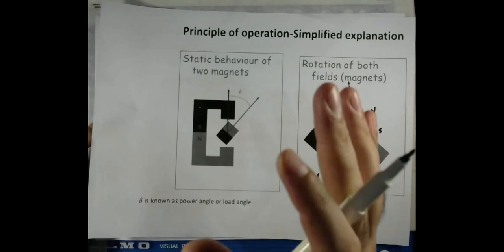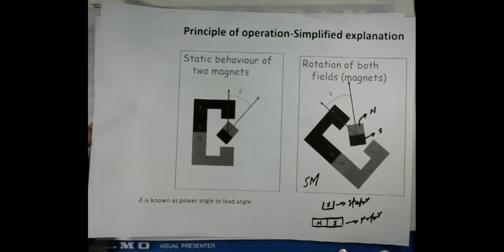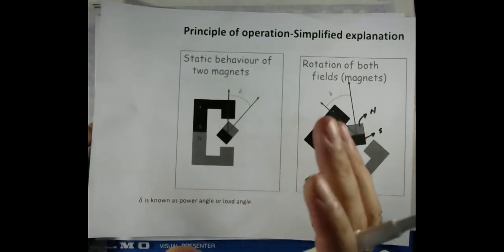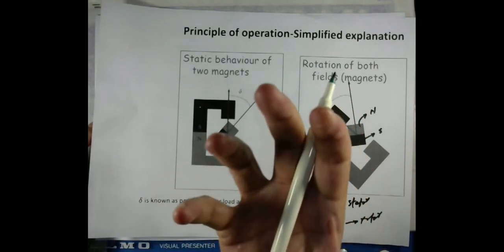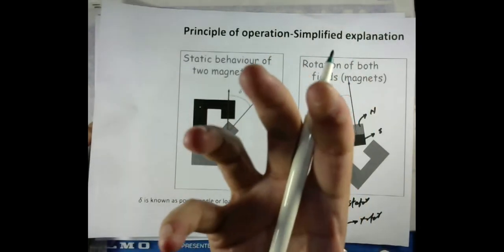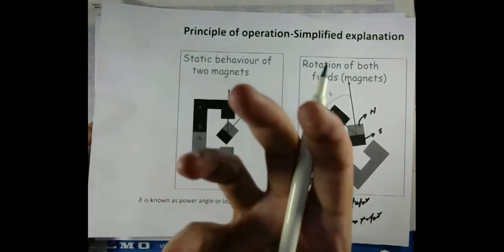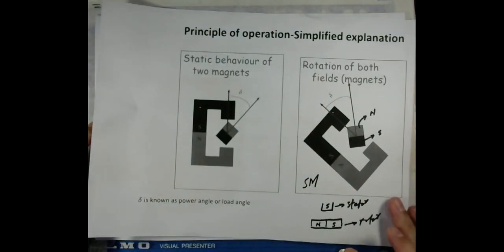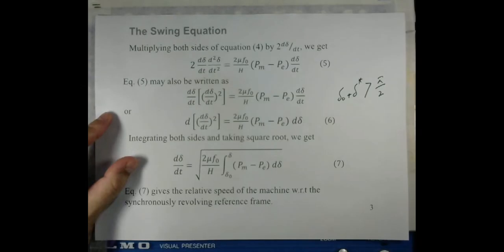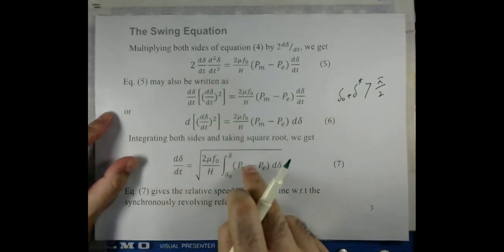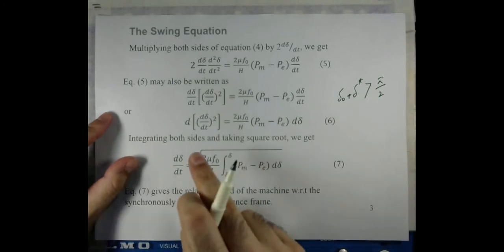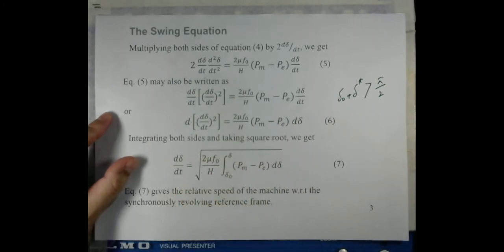So we need to carry out the transient stability analysis in order to check what sort of disturbances the system can withstand, or what should be the amplitude of disturbance that a system can withstand without losing synchronism. So the relative speed must be 0 after the application of the disturbance in order to ensure stable operation.